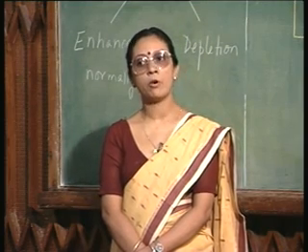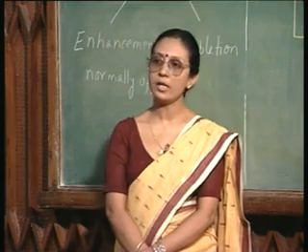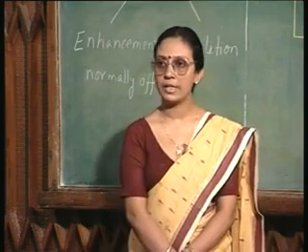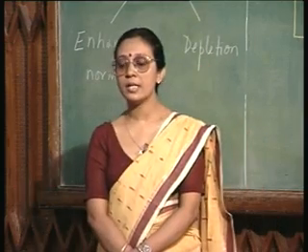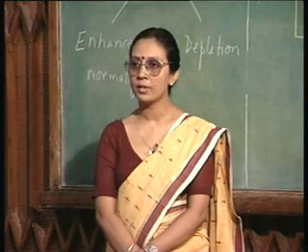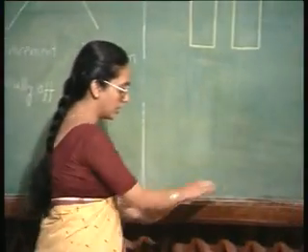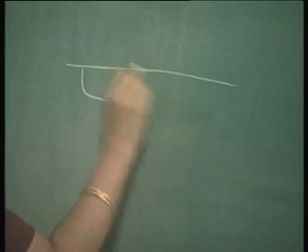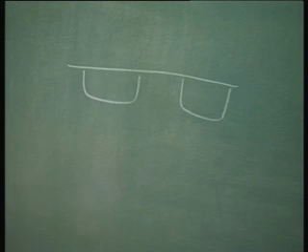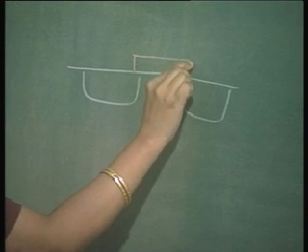It is very important that the channel extends all the way from source to drain. So, what does that mean? That the gate oxide must overlap the source and drain region. In other words, what I am trying to say is something like this. If I have my source here and drain here, then the gate oxide must extend from here to here.